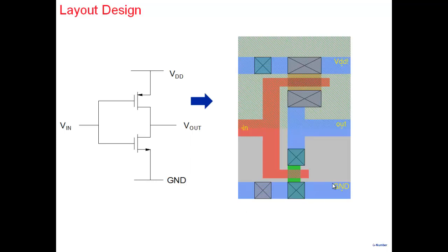So this is where I'm now talking about how the transistor will actually be fabricated. Let's say the layout is ready. The layout is effectively a drawing showing the various layers that are there. This drawing, or the layout, can be digitized. It's available in the form of a file. And once you have that layout file, you can send it to a foundry. The foundry can take this information and fabricate the IC for you.